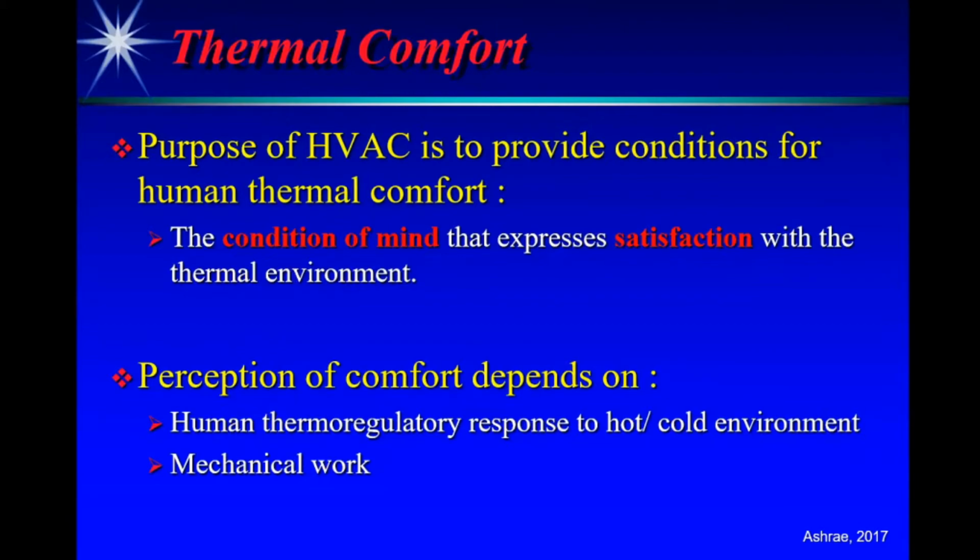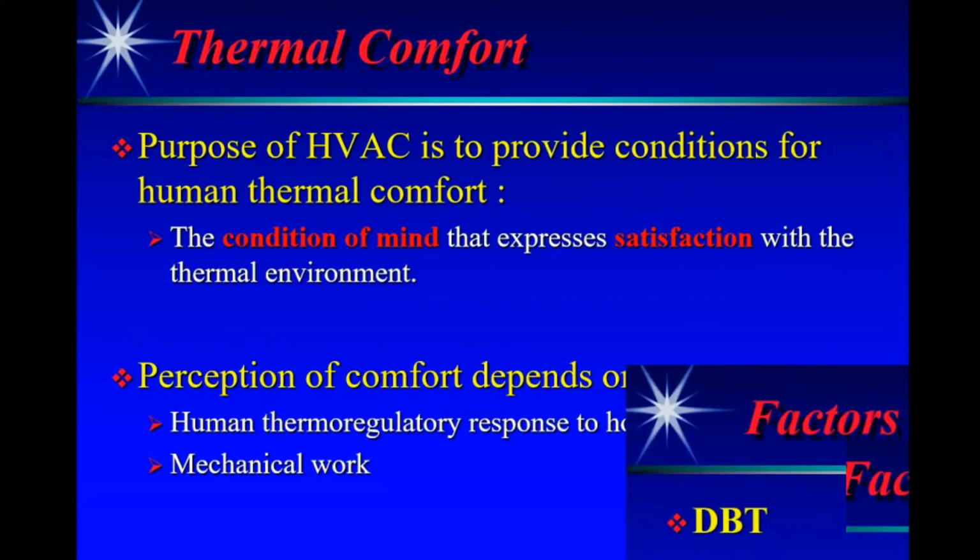And these studies are carried out through surveys, which give an idea of the conditions under which most human beings feel comfortable. It has to be kept in mind there is no condition at which 100% of the occupants feel comfortable. And therefore, using statistics, we try to maintain conditions where 80%, 90% or 95% of the people feel comfortable. So what affects comfort is mentioned again on the slide, which is related to the human thermoregulatory response to any environment, and also the kind of work or activity in which human beings are involved when they are in that particular environment. So these factors play a very key role in perceiving thermal comfort.